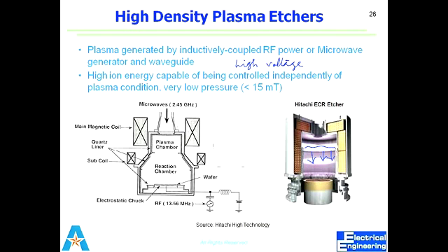Yes, actually the etch rate, you're talking about the high aspect ratio and? High aspect ratio and thin thickness. So in that case, I want better control on the etch rate, right? Even though the aspect ratio is high, I would not go for high density plasma because it would over etch. But actually for the high aspect ratio you need more energy to reach that depth. So I can use a low density plasma with higher pressure, right? It will still give me the same result.